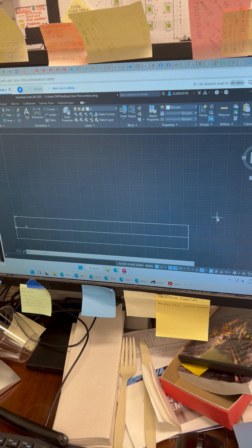Now start the line command. Now you'll probably be able to do it. So here, start the line and that's right. Specify 0, 0, hit enter. Now point straight up. It's 2.1. I'm sorry, 2.5. Now move. There you go. See, now you got your bearings a little bit. Now type in 36. Perfect. Now point it down.